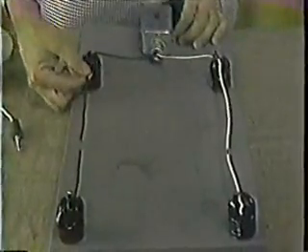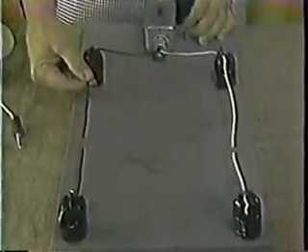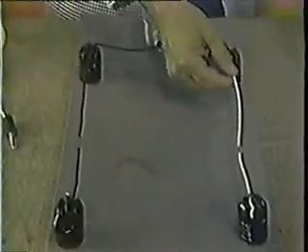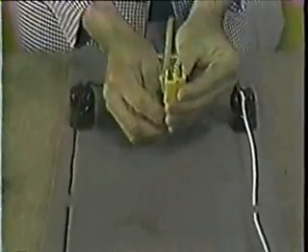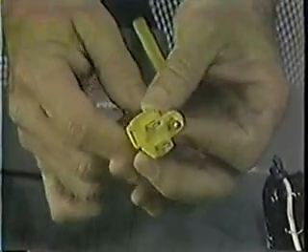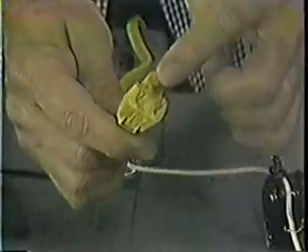With 120 volt single phase, 1 wire is the power, or as it's usually called, the hot wire. The other is what is known as the neutral. It should be noted here that most electrical appliances now have a 3rd wire, which is the ground wire. It serves as a safety in the event of an internal short. The ground is connected to this prong here on a 3-prong plug.